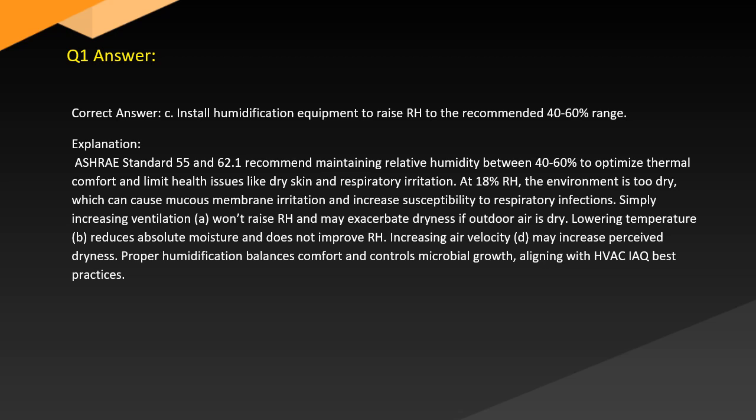Simply increasing ventilation (A) won't raise RH and may exacerbate dryness if outdoor air is dry. Lowering temperature (B) reduces absolute moisture and does not improve RH. Increasing air velocity (D) may increase perceived dryness. Proper humidification balances comfort and controls microbial growth, aligning with HVACR best practices.